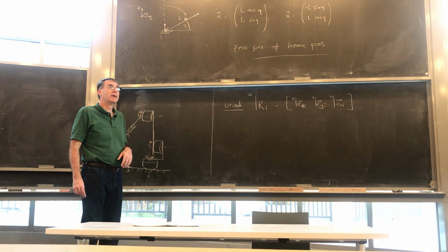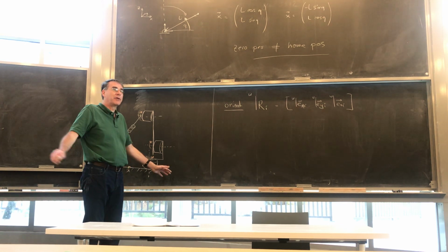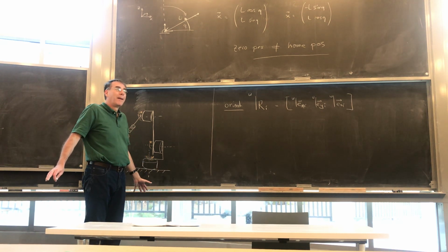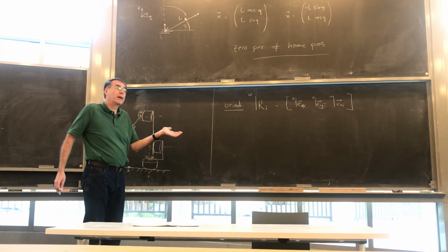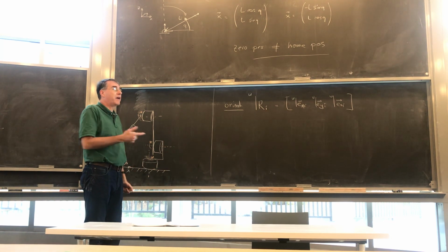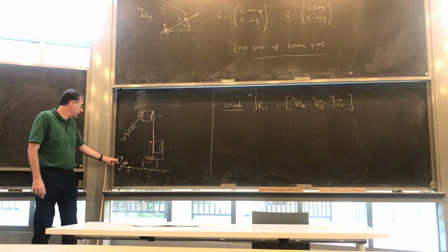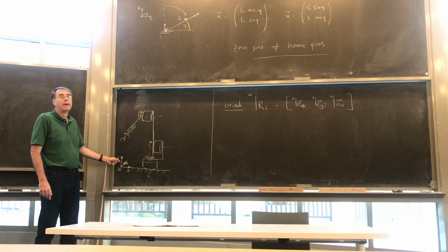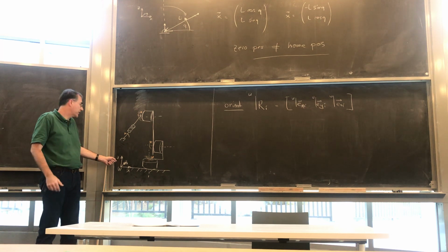What does world frame mean? At some point, I needed to define some reference, some ground truth. Because if I give you a vector, 1.3, 2.4, and 7.9, well, that's a distance from where? So I have to put an origin somewhere in the world, and I've got to define what x, y, z is somewhere in the world. By usual notation, you tend to make z up. Roboticists like z up. Vision people tend to have z go forward and x, y up. Convention.